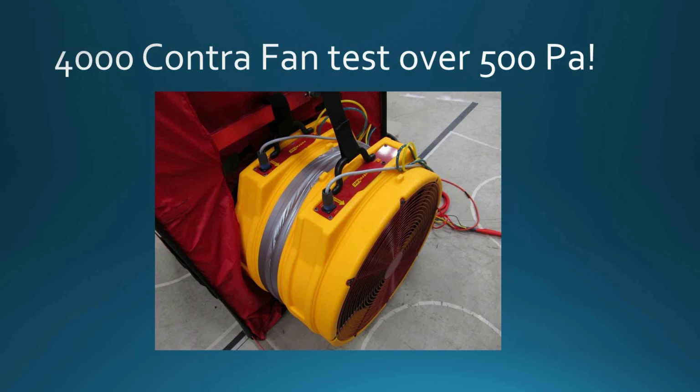So the next thing we're going to talk about is a very key thing that you will find when you're testing these enclosures: if you can, for example, measure the ratio of the bottom leaks to the top leaks, you can often have a situation where the enclosure can be made tight in the bottom to get a good hold time, and a little bit leaky above, which they tend to be naturally. Typical enclosures come in at about 25% lower leaks, 75% upper leaks. If we can measure that under NFPA or ISO for that matter, we can put those numbers in and get the advantage in hold time and also in peak pressure.